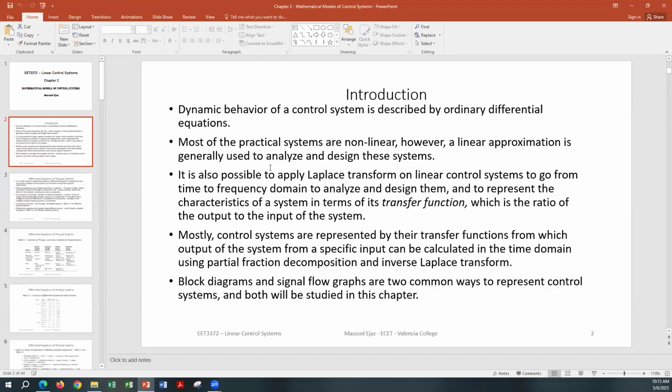Once we have the solution in the frequency domain, we can again find a lot of characteristics without even coming back to the time domain. Your stability characteristics, how to design the system, a lot of stuff can still be done in the frequency domain. But if you want to see the time domain expression and plot it, then you can go back to the time domain from the frequency domain using the inverse Laplace table. And then you can see the time domain expression. Again, writing those expressions and solving those things in time domain itself sometimes becomes pretty complicated.